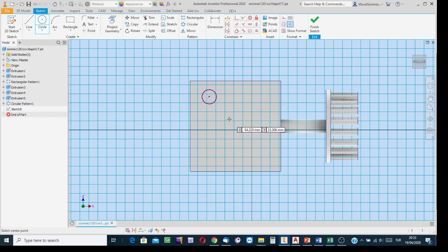First mark the point. It is the point about which the circular pattern is going to be created. In this example, say that the center of the distribution for the polar array is the centroid of the surface. I mark the point using the point marking facility, and then dimensional constraint. Project geometry with respect to this edge, with respect to that edge. Dimensional constraint, from this projection to the point, distance is equal to 100.